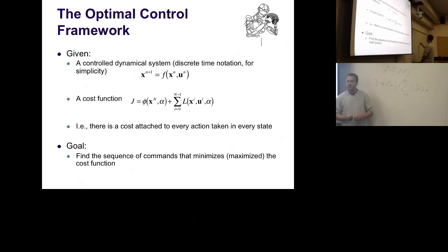So it's actually a very straightforward problem to formalize. You just sum up cost terms along the trajectory. They depend on the state, they depend on the motor command, they may depend on some parameter settings you have. These parameters are kind of generic parameters. For instance, you could put the gains of a PD controller into this optimization framework and say, I give you a penalty if you need to use high gains. But then you keep the gains constant over the entire horizon. You see they're not indexed by i. So these refer to parameters which are valid for the entire time horizon. These are terms which are just instantaneous at every time step.